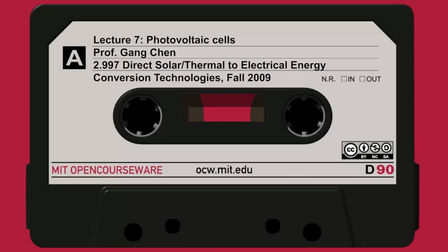And of course, you can look at this. The power output is the voltage times current. So somewhere, your voltage times current, that's this squared. Depending on which point you're operating at, you'll have a maximum. And that's how you optimize. You change your load resistance, so that you can control the current and the voltage by changing the external load resistance. So that's a load measure.